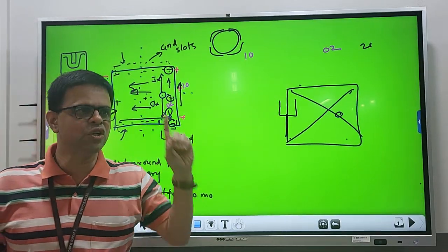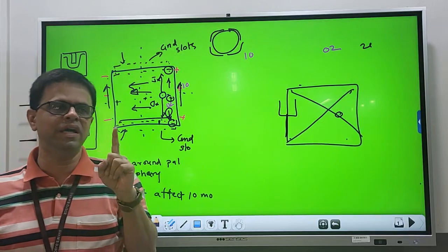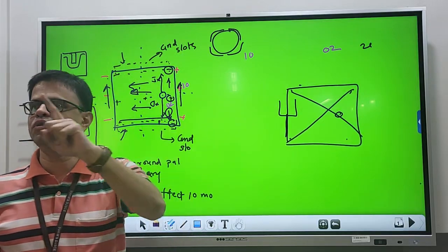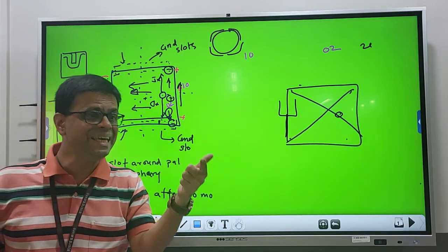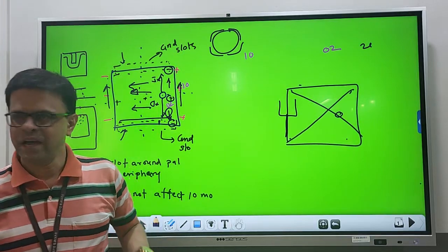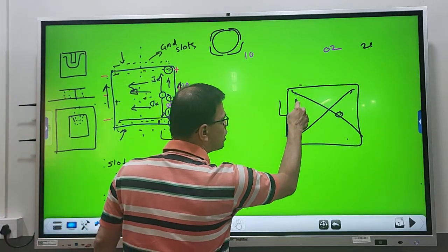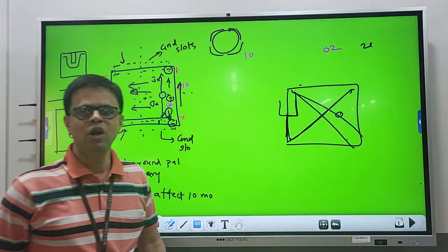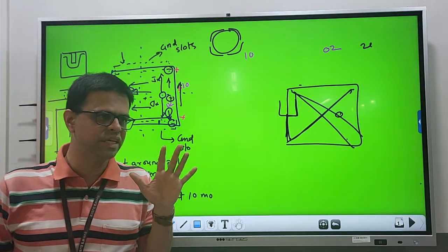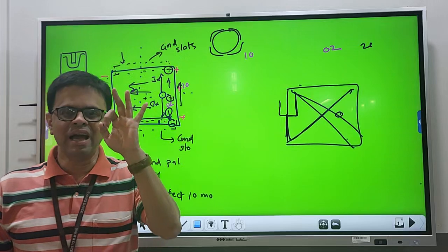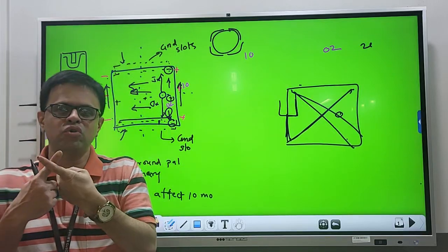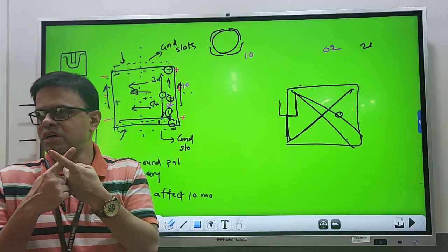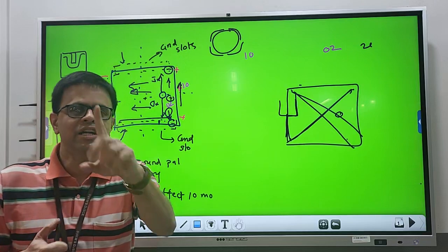So the creation of two unequal diagonal lengths relates to the creation of two diagonal modes, what you have seen in the U-slot cut antenna. Again I repeat, when you are cutting this slot, remember this is creating unequal diagonal lengths along the patch's two diagonal sections. So that creates the two orthogonal modes on the U-slot cut defected ground plane patch, and that leads to a CP response.